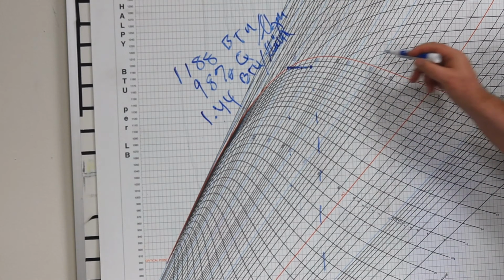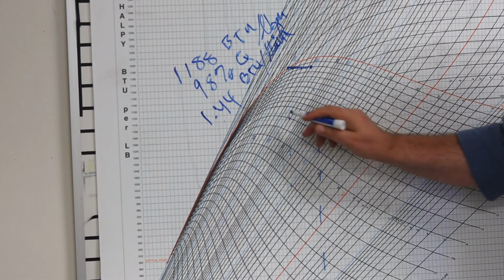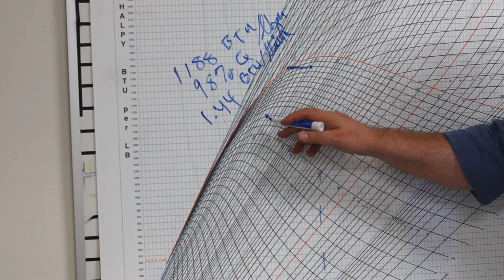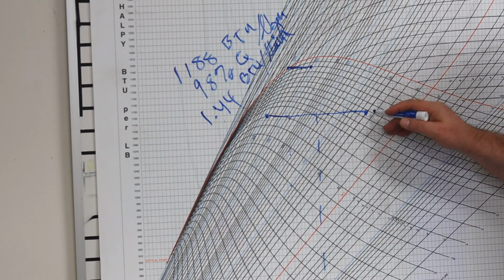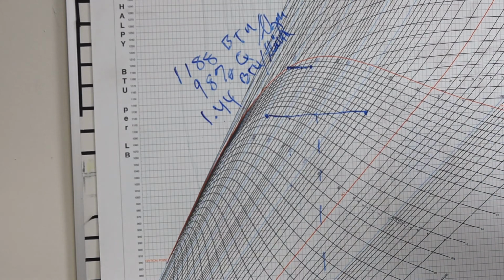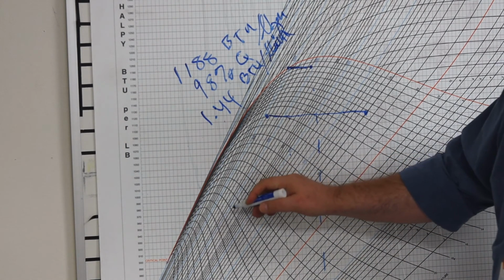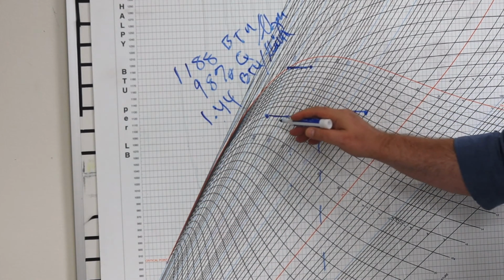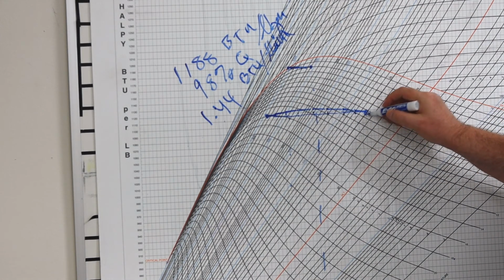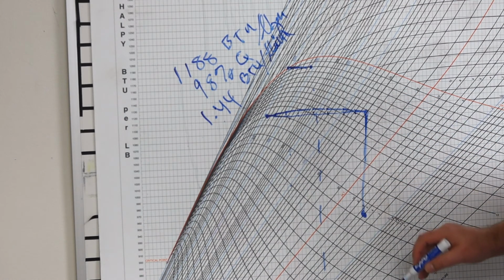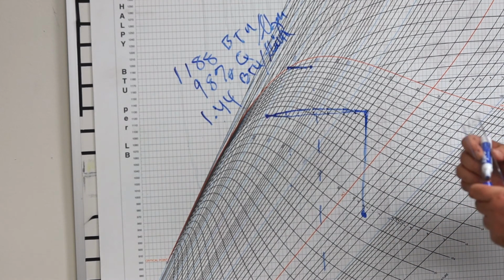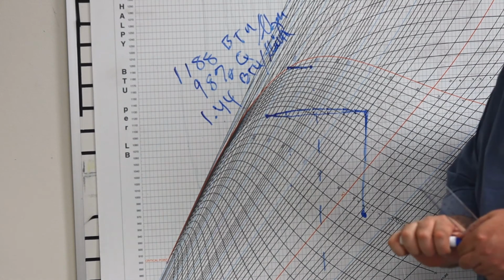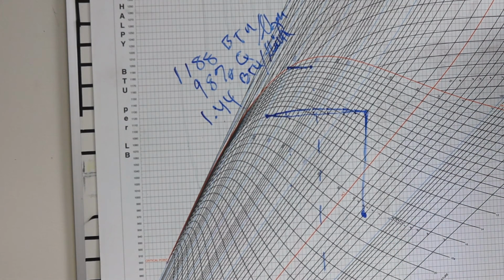So once again, a throttling process is a constant enthalpy process and goes across. If I gave you a point right here and said you're going to throttle through some valves until it's 50 pounds, you're going to draw a line straight across till you get to your 50-pound curve. And to jump a little bit ahead, this week we're covering thermocycles. If we were actually having you plot some of those, I would give you starting conditions outside of the Mollier diagram, where you end up here. Then you have to figure out the throttling process across here. And then from here, what's the work process? How much work was done by a turbine when we exhaust to a condenser, right? So you would go through and plot out an entire thermodynamic cycle, and you would calculate each leg of this. But we're not going to get into that. We're just going to focus on the concepts and do the processes one leg at a time.